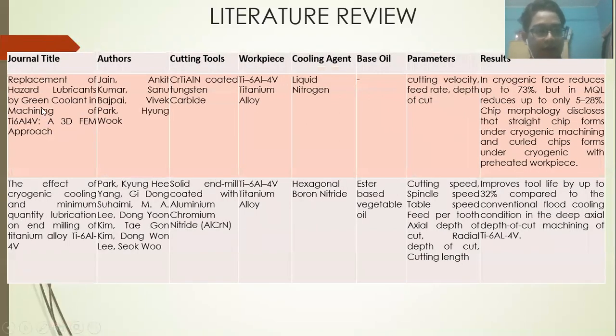Next is the replacement of hazardous lubricant by green coolant in machining of titanium alloy. The cooling agent is liquid nitrogen. The workpiece is titanium alloy. The method is still using cryogenic cooling, and the result is reduced up to 73% in force, but in MQL, it reduced up to only 5 to 28%.